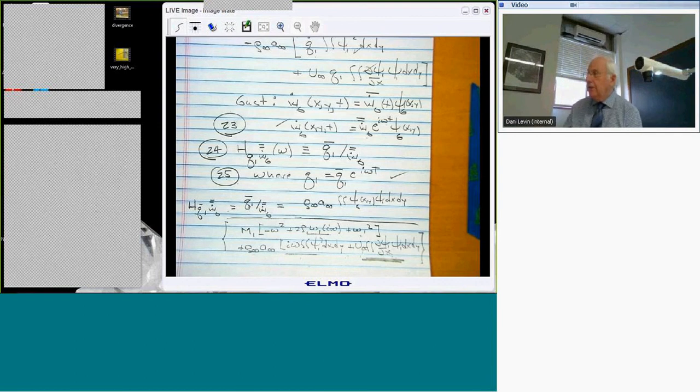The aerodynamic theory isn't as good at predicting aerodynamic damping as it is in predicting aerodynamic stiffness. So the theory is much more reliable in predicting this kind of term rather than this kind of term. Actually, for piston theory, this is usually pretty good, if you're in the Mach number range where piston theory is supposed to work.